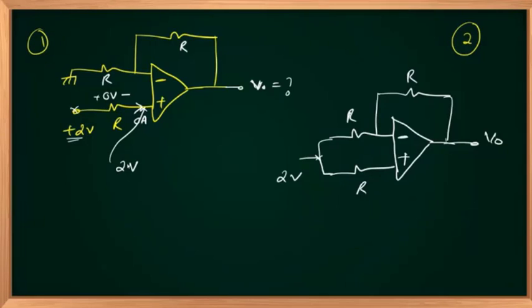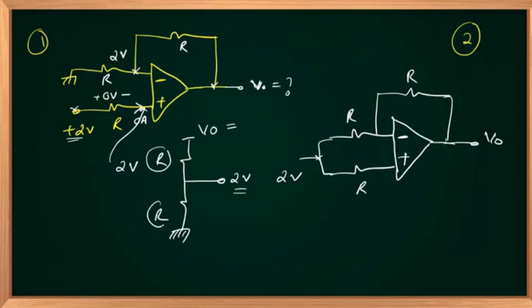Ashwin says 4 and 0. Very good. 2 volts here. And with negative feedback, this should be 2 volts. This is V out, with 2 equal resistors, R and R. This node I understood to be 2 volts because the minus end is grounded. Then how much should my V out be? To get 2 volts between equal resistors, I should apply 4 volts. So this is nothing but 4 volts.